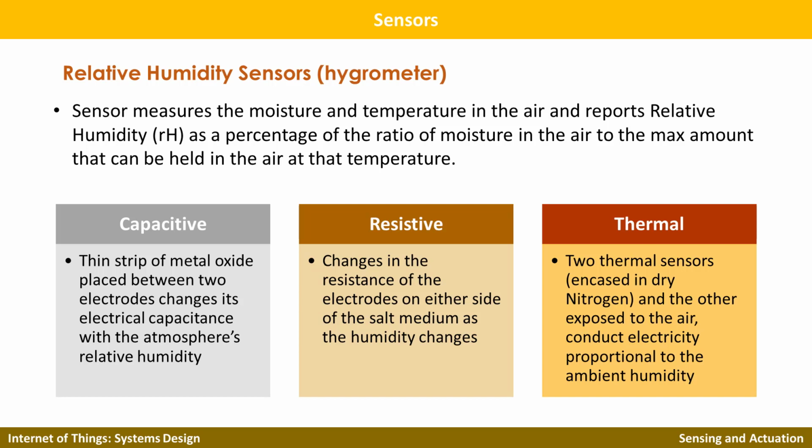For example, weather, commercial, and industrial applications use these types of capacitive humidity sensors. Capacitive type sensors are linear and can measure relative humidity from 0 to 100%. The downside is the complex circuitry, and regular calibration is required.